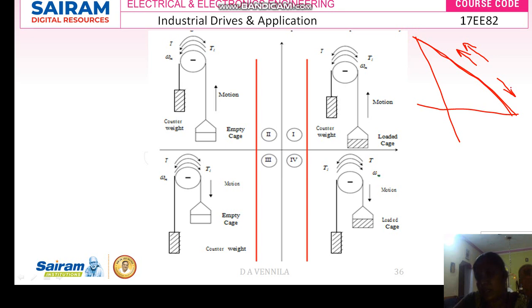And what does this mean? Here due to force of gravity, the load torque is moving towards the down, that is due to force of gravity. Here the load torque is pulling down, but the motor is producing the torque which is enough to make the car move towards the uphill. Also your speed is towards up. This motor torque should be greater than your load torque.